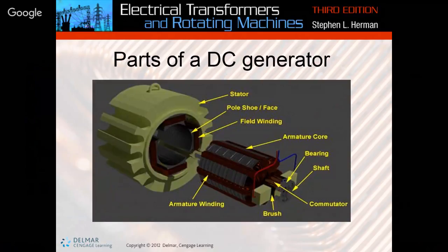Actually, the ECM motor in HVAC is a brushless DC motor. It gets fed in with AC power. It gets translated from AC to DC right inside of there, and it's all contained in that one motor. So they're really neat. Okay, any other questions?